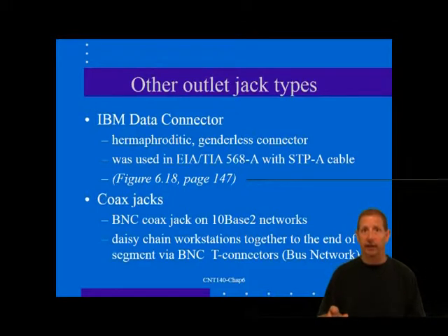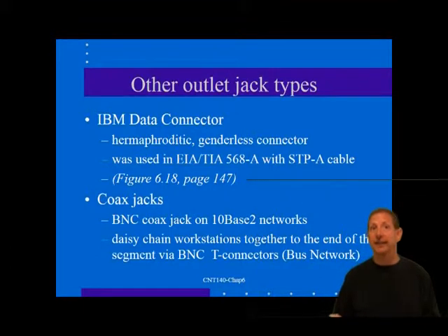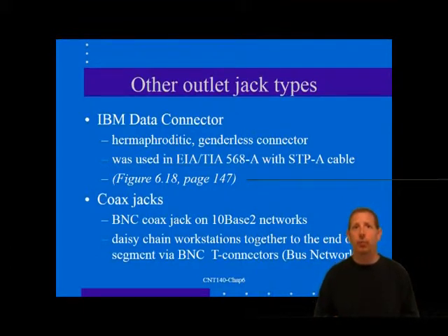The color codes for the horizontal 150 ohm STP-A cables are by pair colors. Pair 1, red and green. Pair 2, orange and black. This color code corresponds to the markings for the IDC contacts within the data connector and makes the cable conductors very easy to match with their proper contact. The data connector outlet is a version of the standard data connector that is mounted in a cover plate.